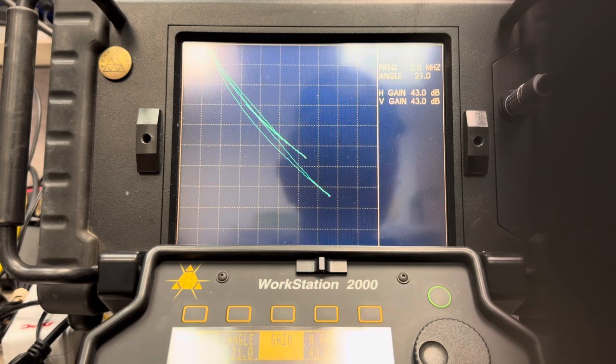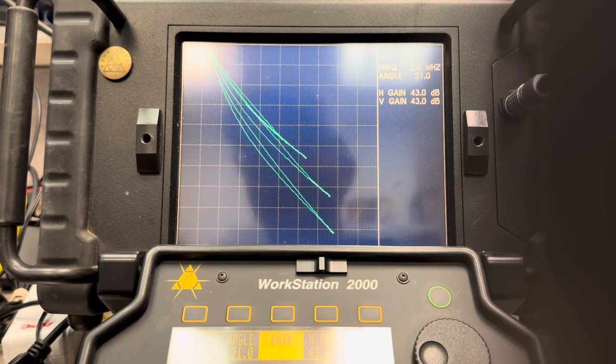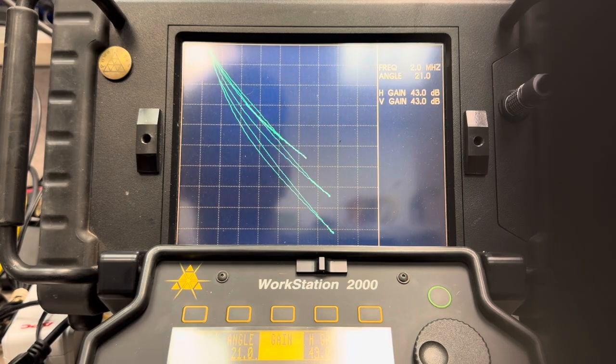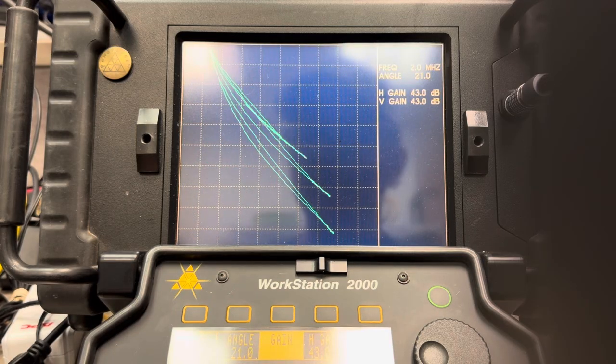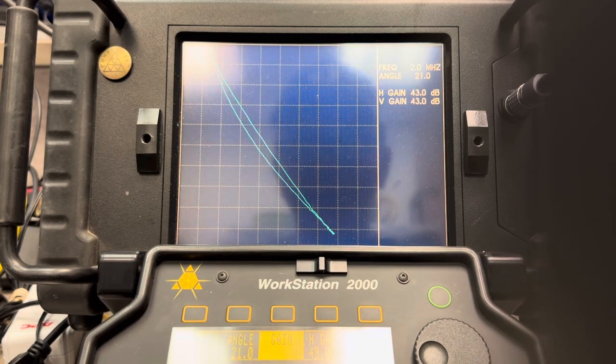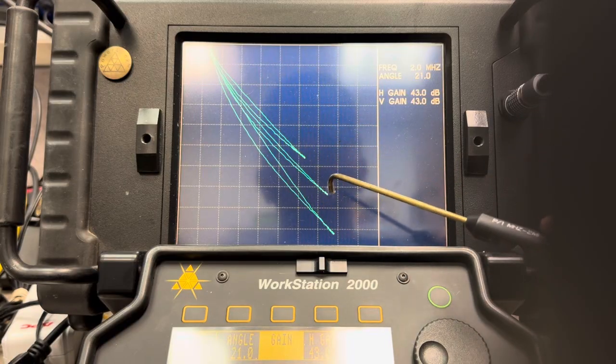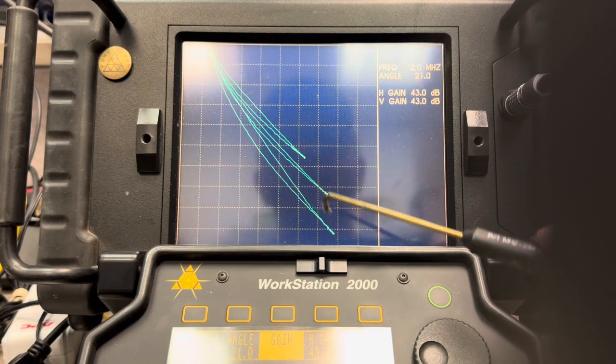What if I touch some other materials? What about copper nickel? That's not super conductive. Looking at the slide rule, yeah, it's only 8% IACS. So let's do that again. Copper nickel, titanium, and what was the other one? 304 stainless. These are three distinctly different impedance positions.